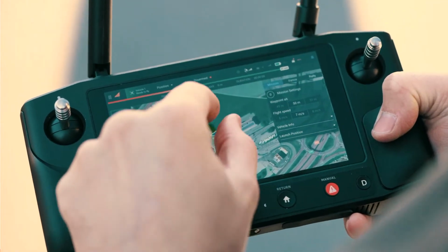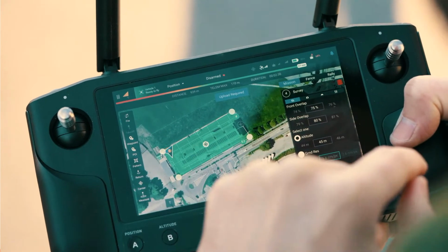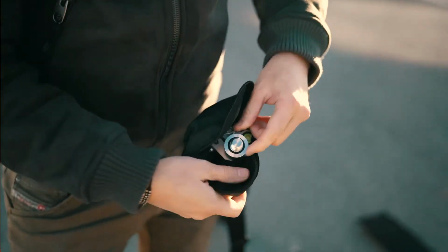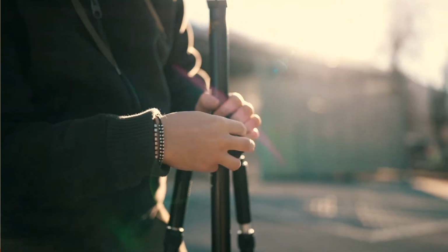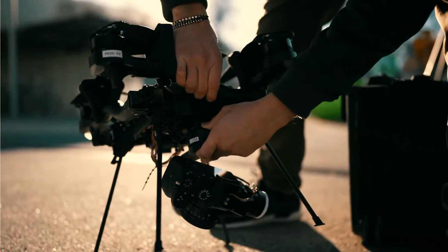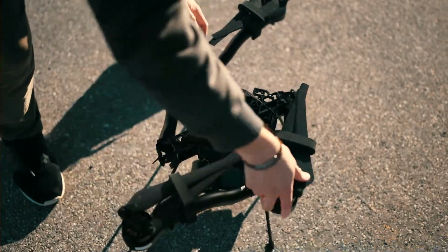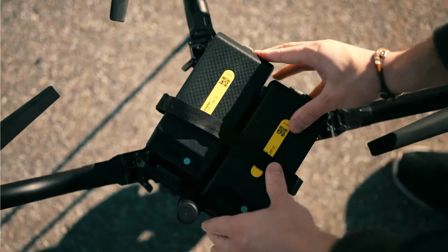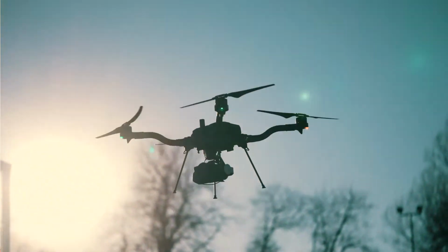For that particular mission that we flew last week, we did the planning directly in the field on the controller. I mentioned it before, we could have done it on a laptop as well. In the field, the preparation also included using a ground GPS, a base station. This is something you can use to increase the accuracy of the geotagging of the images. Something I haven't mentioned before: all the pictures that the Astro is taking with the Sony camera are geotagged on the Skynode before they're delivered to the cloud. So the images you take off the vehicle are already geotagged, but you can of course also improve the accuracy using these base stations.